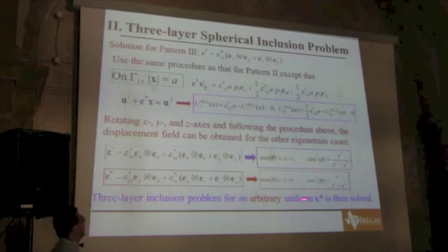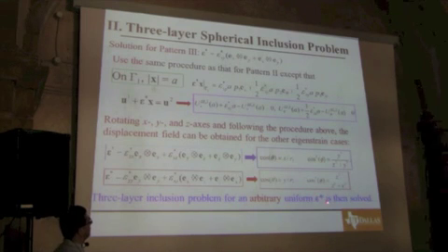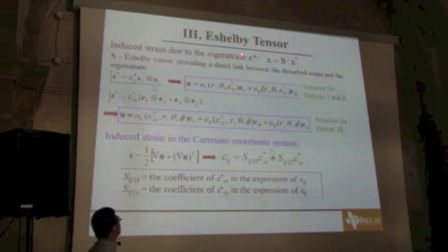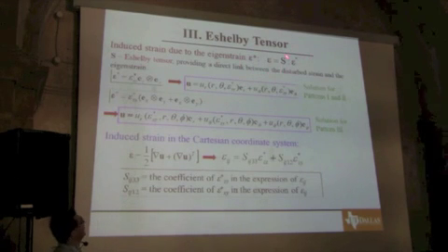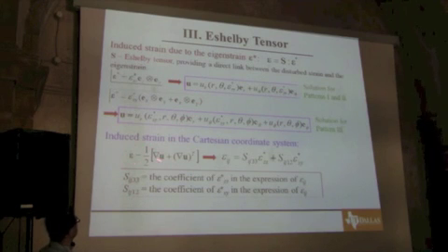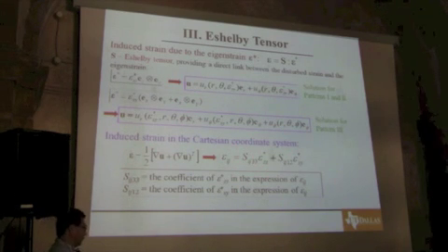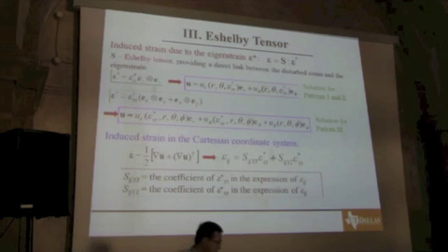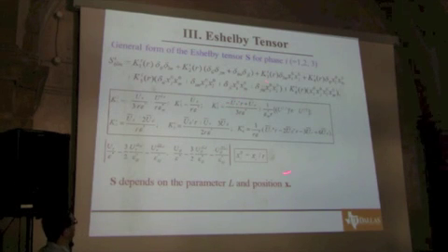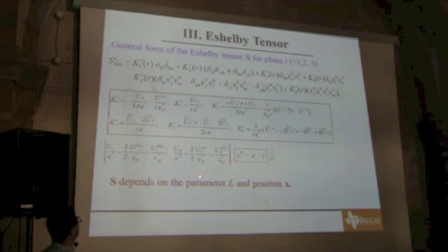So that will help us to solve any problem with a prescribed arbitrary eigenstrain with all 6 non-zero components. Now we can go ahead and compute the HB tensor according to the definition given by HB. We simply evaluate the displacement field and then calculate the strain, and the coefficients will be the components of the HB tensor. I'll skip the details, and this is the general form. It's quite complicated. It would take pages to write each and every expression. So these are the general expressions.